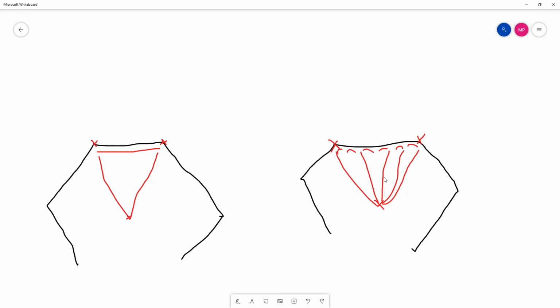And the reason I have these lines here is I'm hoping to represent the fact that as this goes along, it has an X coordinate, a C coordinate, and a Z coordinate, and then an X, C, and Z coordinate for that to make that line. Each one of these is actually a different X coordinate because it's actually changing the radius of that rotary as it goes along to maintain that somewhat of a line there.